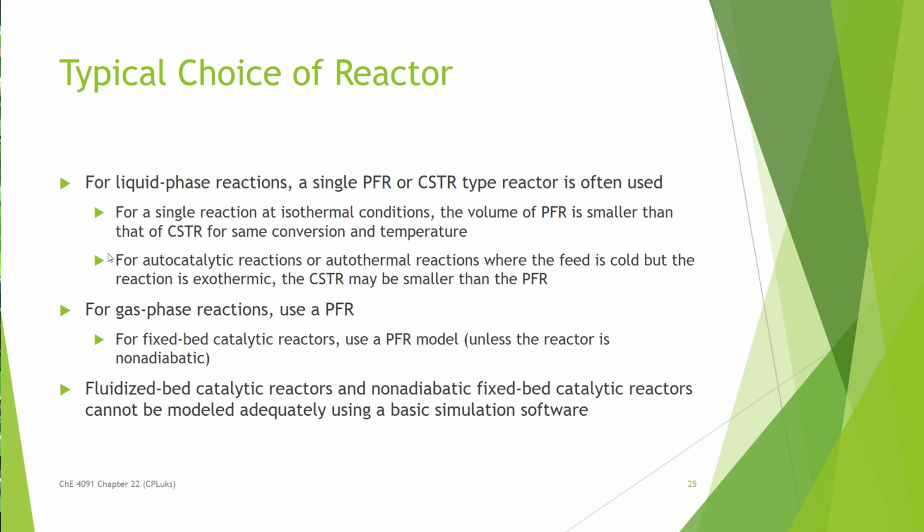If you have a fixed bed catalytic reactor, use a plug flow model unless the reactor is non-adiabatic. Fluidized bed catalytic reactors and non-adiabatic fixed bed catalytic reactors really aren't going to be modeled all that well using basic simulation software. Some more advanced software may be required to get a good model.